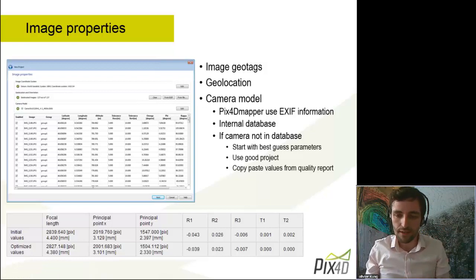However, if your UAV geotags are taken by a standard GPS, very likely they will be in the WGS84 coordinate system. In that case, by default, and if you don't have any GCP, the results will be in the UTM coordinate system. However, if you select another coordinate system for your geotags, then all the results will also be in that specific coordinate system, except if you have GCP.